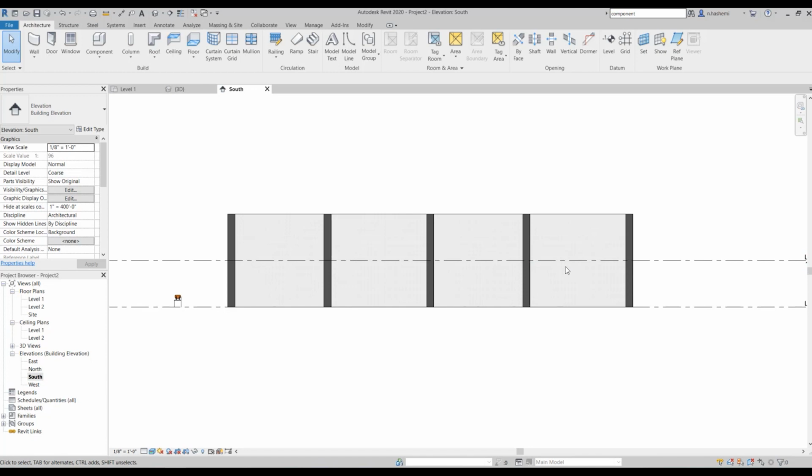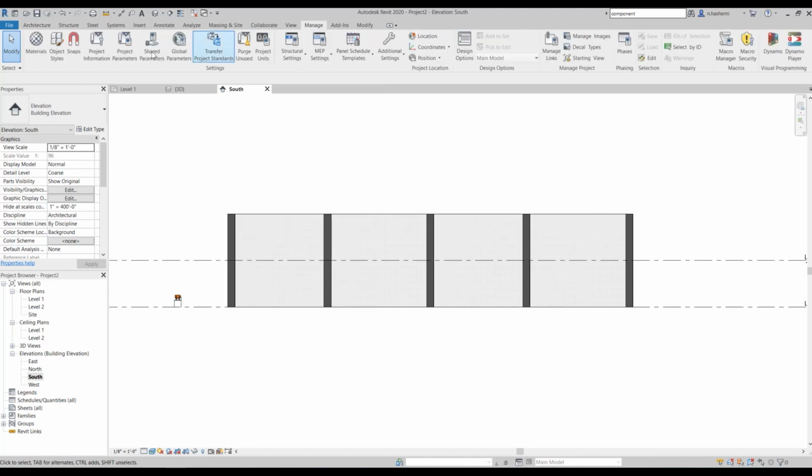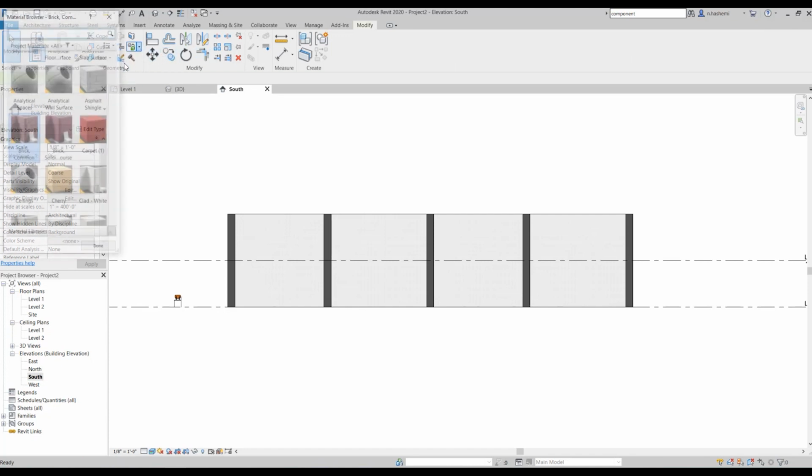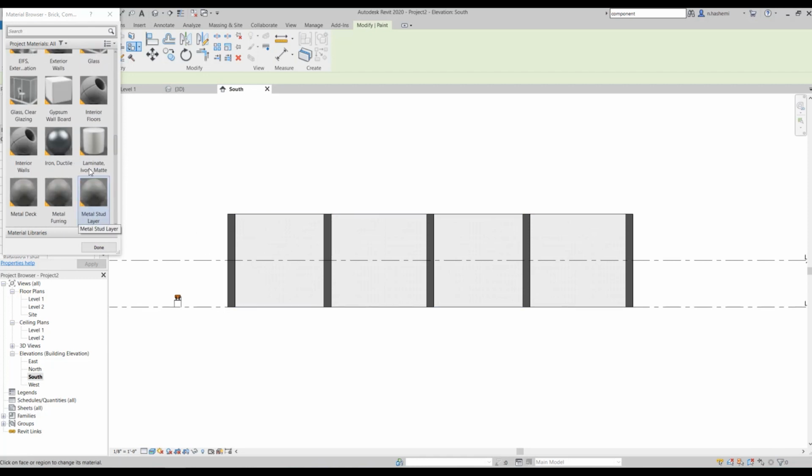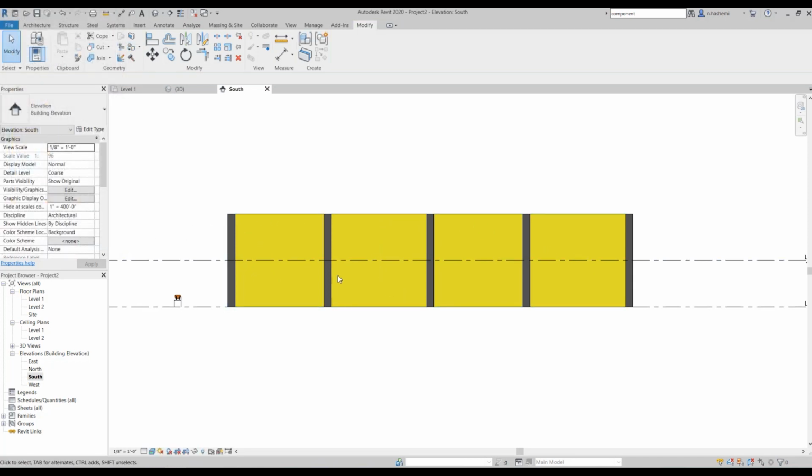Right now, if I choose the paint tool and change the color of this face, let me choose a color, this one for example, you can see that the whole face color has changed. So we don't have the walls of these offices separately. Adding these partitions over here will not divide the back wall automatically.